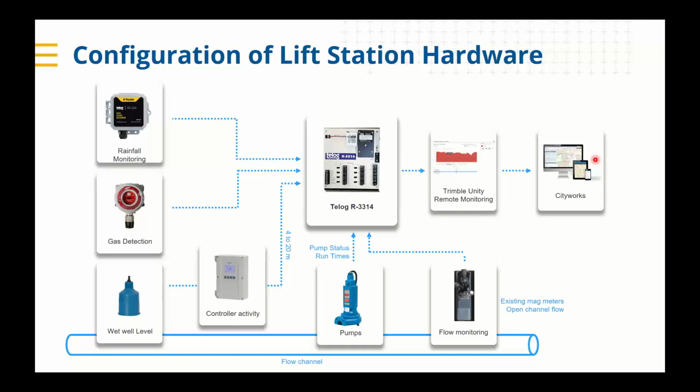One thing, we don't do any controls. We can just monitor what's going on in the system, so we don't have the C part of the SCADA. We can just do the data acquisition. We can track pump status and run times, and we can also track flow monitoring. So if you guys have existing mag meters out in your system, we can tie that into one of our units and get the actual signal from the mag meters and track those as it goes along.